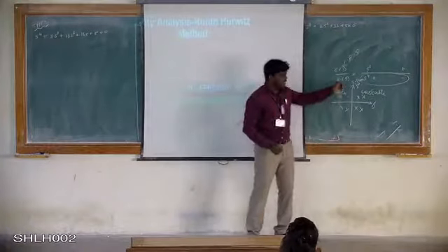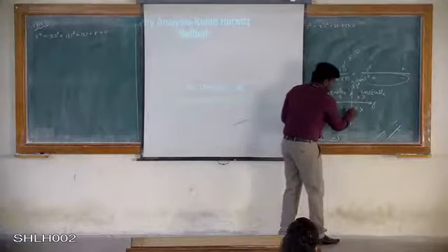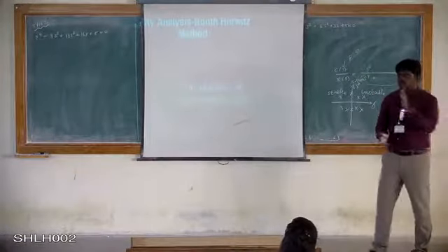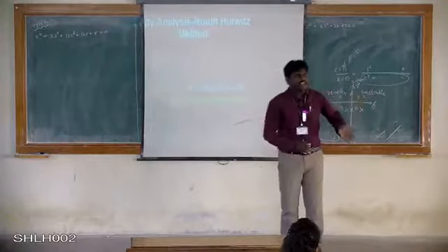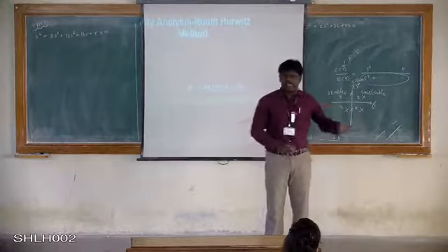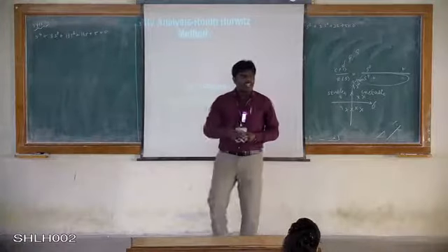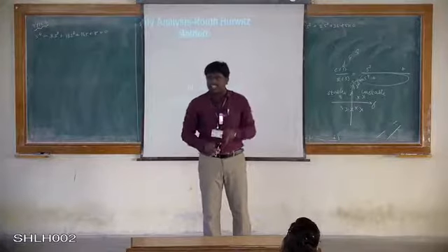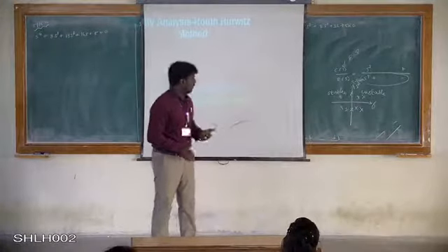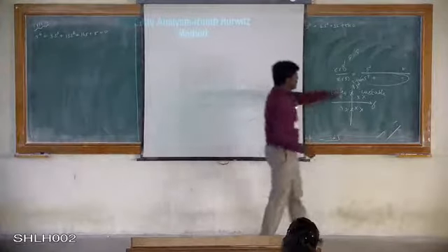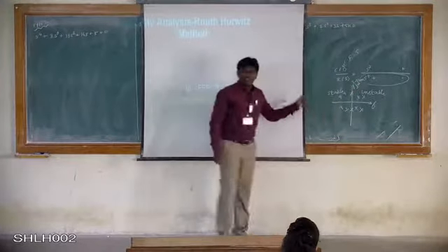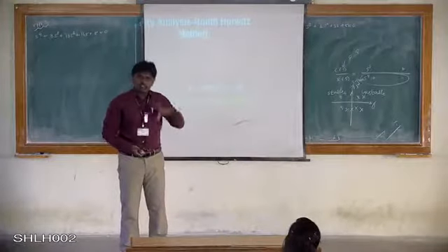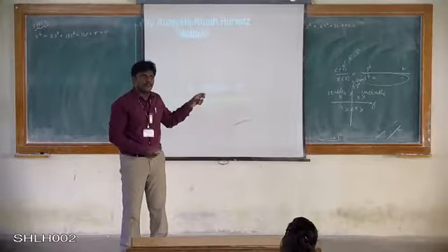Okay. Even if the roots are lying on the imaginary axis, then the system is said to be marginally stable. So the roots lying on the left half of the S plane mean the system is stable, and the right half of the S plane means the unstable system. The roots lying on the imaginary axis mean marginally stable. To get all these root values, we are supposed to solve the equation, get the roots, and go on to plot them, right?